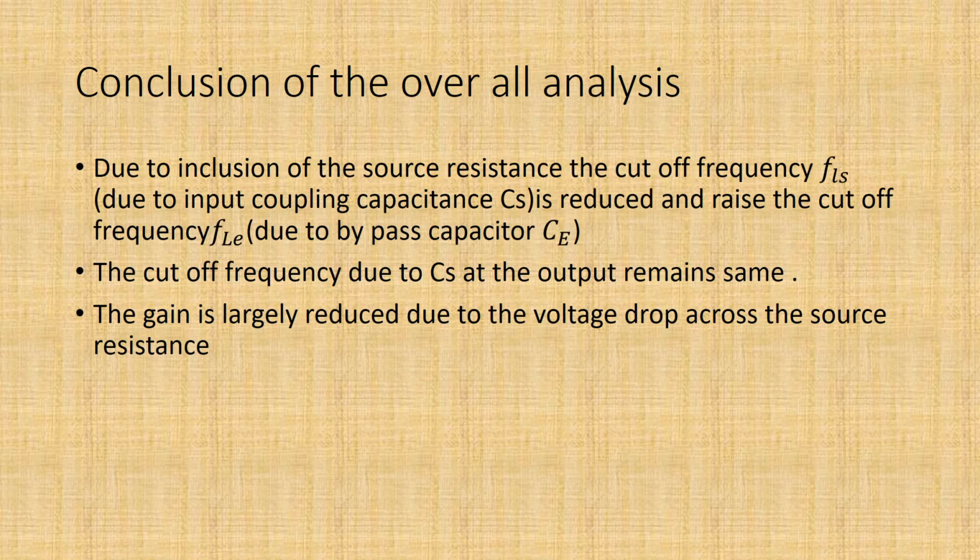Conclusion of the overall analysis. Due to inclusion of source resistance, the cutoff frequency FLS is reduced, but the cutoff frequency FLE is increased. The cutoff frequency due to CS at the output remains the same. Gain is largely reduced due to the voltage drop across the source resistance.